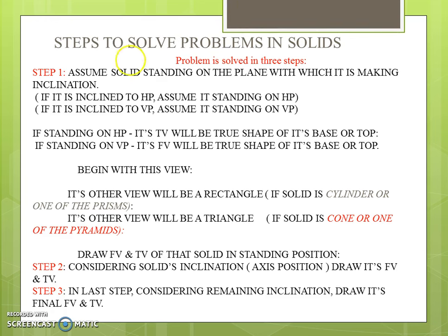So if the solid is standing on a plane, or the axis is perpendicular to HP. If the axis is given inclined to HP, first assume that it is standing on HP. If it is inclined to VP, assume that it is standing on VP.